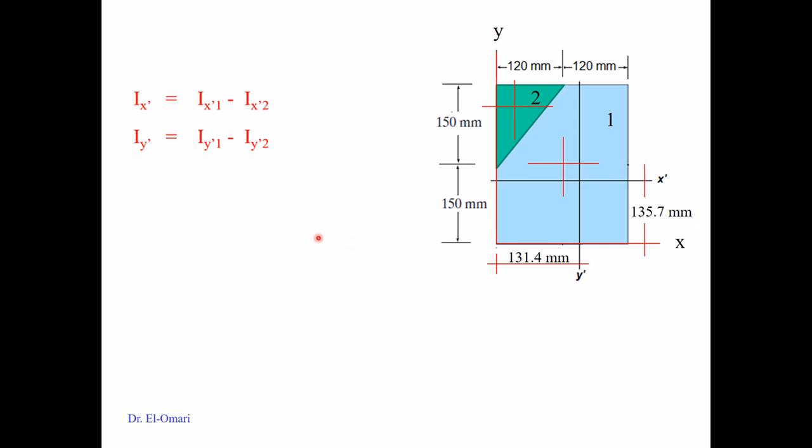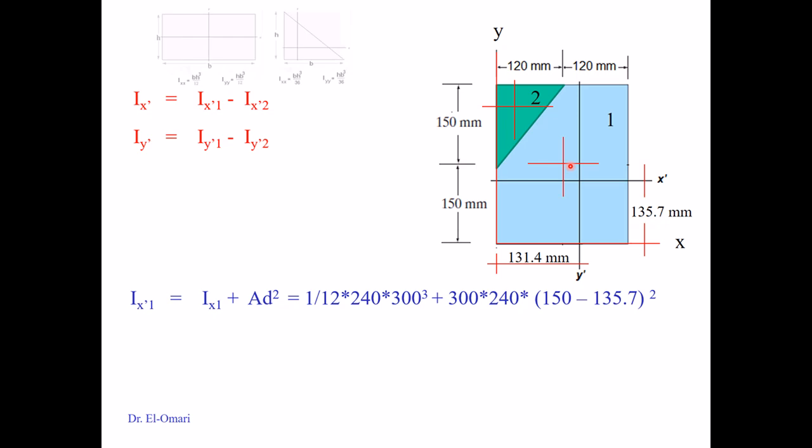So the moment of inertia is calculated now here, as you've seen in a few slides before. You have to use the parallel axis theorem. You have to find the moment of inertia of the whole cross section about its own centroidal axis, and then relate it to the whole cross section centroidal axis, which is that xy, which we know now the location of. To do this, the first part is about its own centroidal axis. You will find in most books, in the tables,